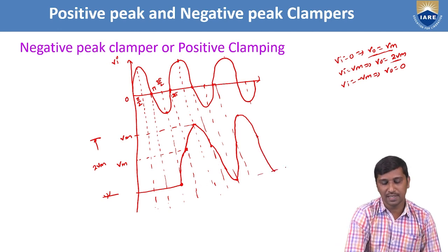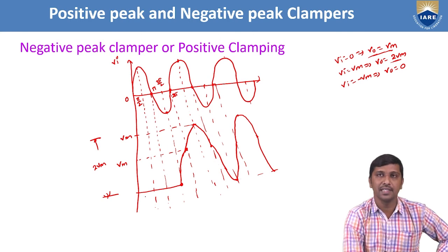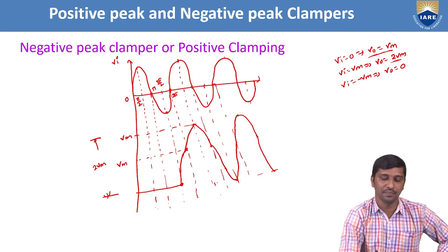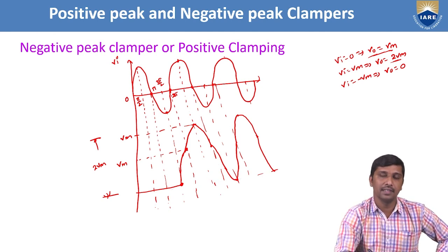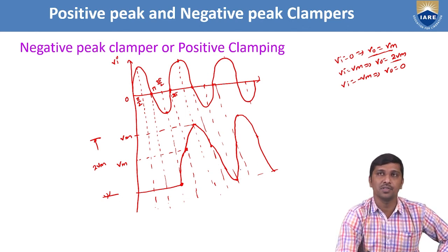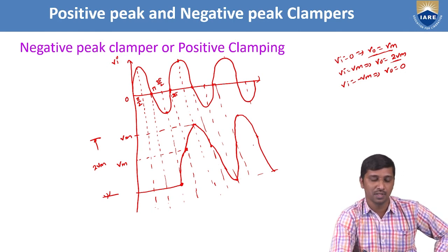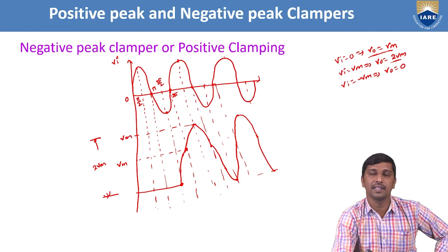So subsequently, you can observe that only in the initial clock pulse, the initial stage, the diode is non-conducting up to this point. Once the diode is conducting, it automatically generates the periodic signal waveform. So now this is the response of the positive clamping circuit. You can observe this input and output. There is no change in the response, only the DC level adjustment.